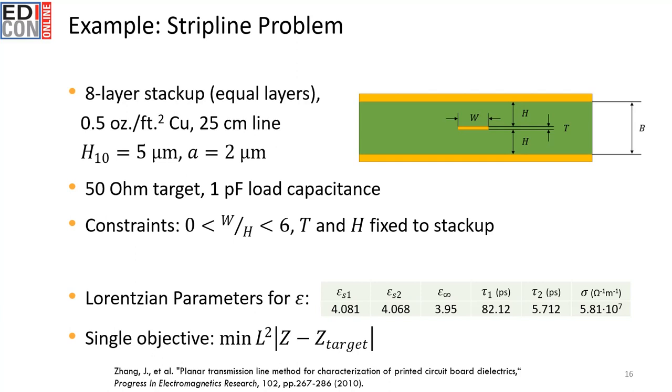So it's this width divided by height. And then we have our parameters for our dielectric constant. So here I'm using a 2-pole model. The standard model is a wideband Debye model. Again, this is just a wideband Debye model, but summed up to 2 terms, because those are the only 2 terms that really matter in our bandwidth. And so the bandwidth, you'll see in the next section, is taken out to, I believe, 10 gigahertz.